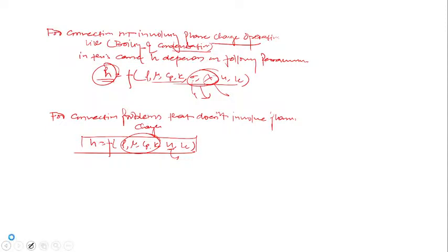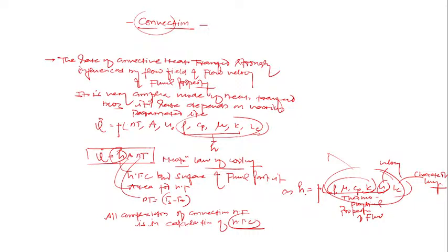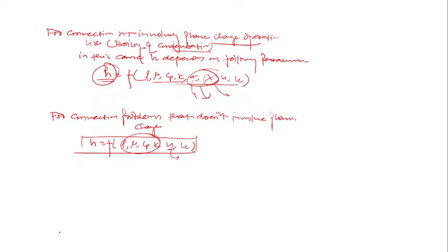That's why I told you this convection heat transfer is strongly influenced by the flow field or flow velocity. Whether it is a laminar or turbulent flow field, depending upon that, the heat transfer coefficient will change for the given fluid. Clear? What does it mean here? For example, suppose you have a hot boiled egg you want to cool. One case has stagnant air without any bulk motion, another has air with some velocity. The air is the same, which means the fluid is the same.